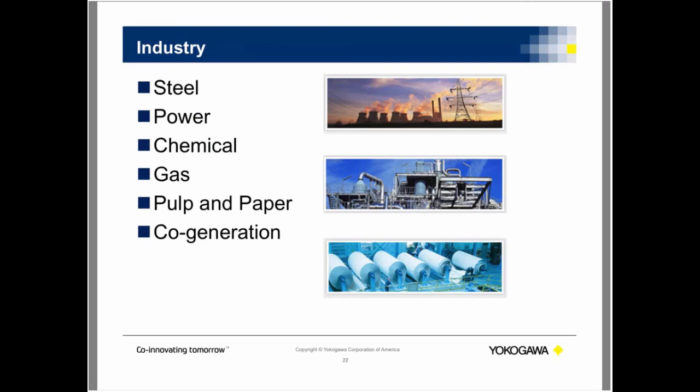Now for the steel industry, sometimes the manifold systems regulate the pressure and the flows of fuel gas and oxygen from the main supply to the cutting torches. And that's mainly found in steel mill and foundry applications. Most of these industries use them to improve layout with fewer hoses and connections. They also use them for increased energy efficiency with shorter flow paths, allowing for minimizing pressure drop and heat. So that's mainly what they use these manifolds for. Manifolds are really good for these industries.